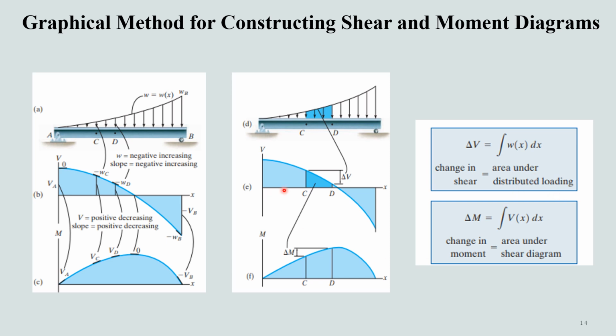So the area under this loading shows the change in shear between the points C and D, and the area under the shear diagram between the points C and D shows the change in moment between the points C and D. Since these equations are not applicable to points where a concentrated force or couple moment acts, in the next slide we'll consider the case of concentrated forces and moments.